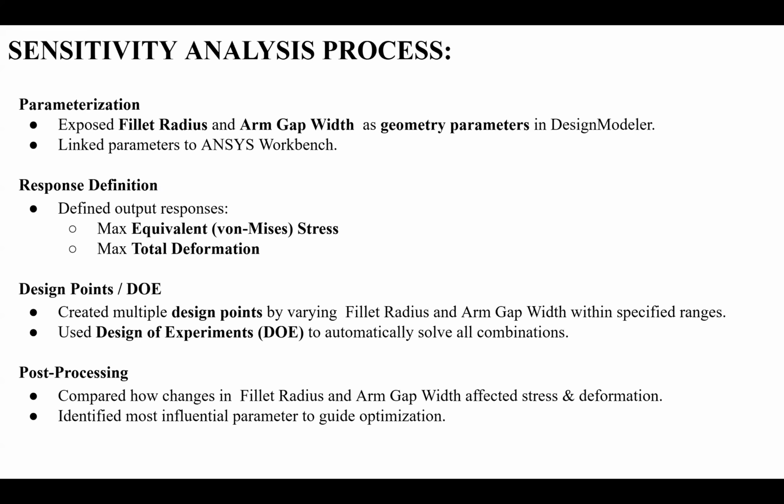Now, moving on to the sensitivity analysis, which forms the major part of our design improvement process. In this project, the goal of the sensitivity analysis was to understand how different geometric parameters influence the performance of the rocker arm, particularly maximum deformation and equivalent von Mises stresses.